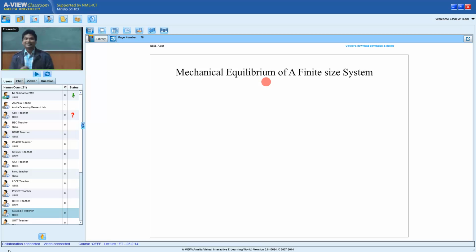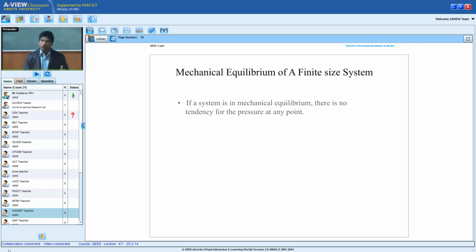And not only that, there is another confusion when it comes to mechanical equilibrium. You take the atmospheric air, the standstill air. One layer of air is above another layer, which is above another layer. And if I take a glass of water, the water is in equilibrium from top to bottom. The water is not moving. Can I say the pressure is the same throughout? No. The dead weight is adding to it. Sometimes mechanical equilibrium occurs when the pressure varies according to hydrostatics or Pascal's law. If the force varies more than the law allows, then equilibrium will be disturbed. That's why mechanical equilibrium requires a lot of deeper understanding.